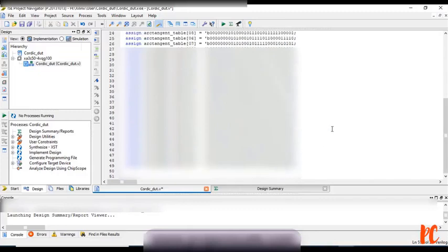After storing the values in the lookup table, let me assign the value to the quadrant. Assign quadrant is equals to angle, with one particular angle, 31 down to 30, I am assigning. Finally I am going for the procedural assignment statements now. Always at passage of the clock, begin. Let me take the case statements.